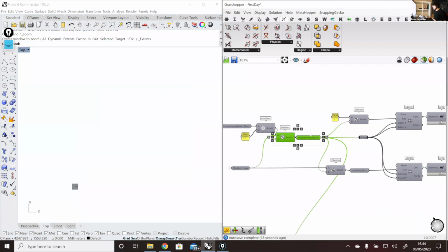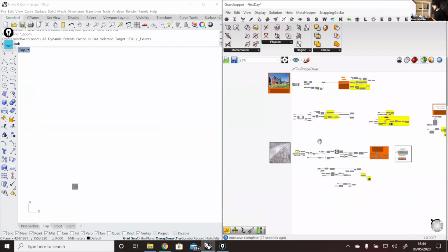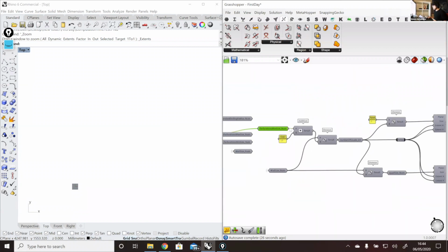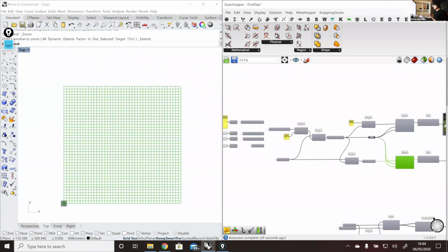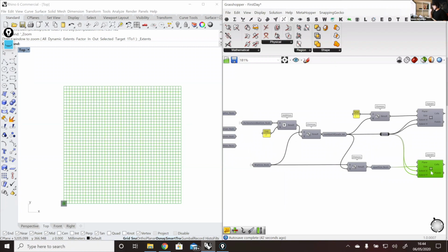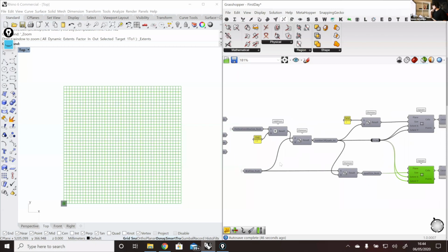So basically here we're just creating a grid. If we check this grid here, in it we know that one of our drilling holes can go. The size of each of these quads in this pattern is as big as the biggest perforation that we can allow, plus some gap, so that we avoid any intersection between different drilling holes. So we sum that up, and then we divide by the wall size, so that we know how many drillings we can have in both directions, in the height and in the width of our wall. So we have here the number of quads.